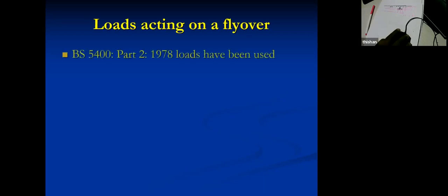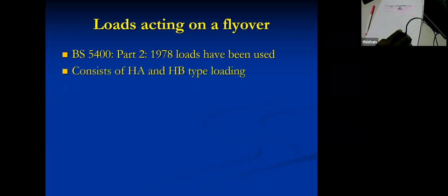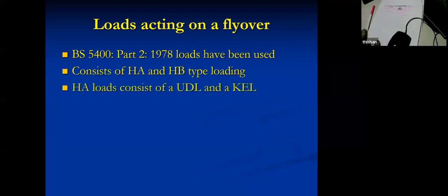But the common detail is T16 or H16 as the bottom mat in the longitudinal direction, and then transverse direction T12 at 150, and in the top mat in the transverse direction T10 at 150, T12 at 150, and in the other distribution direction you can even use T8 at 150. So you can see a deck slab will have a lot of reinforcement, and because of this reinforcement, you will find that it can actually give a very robust